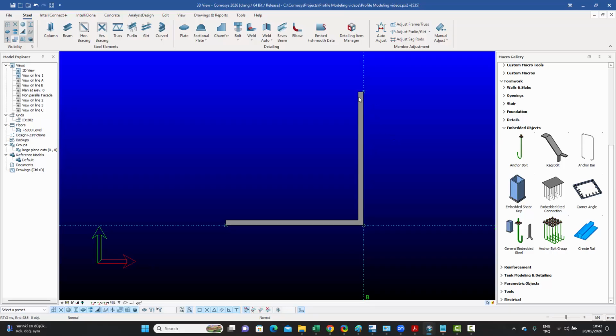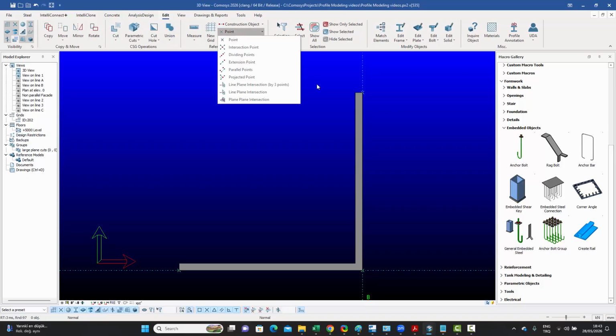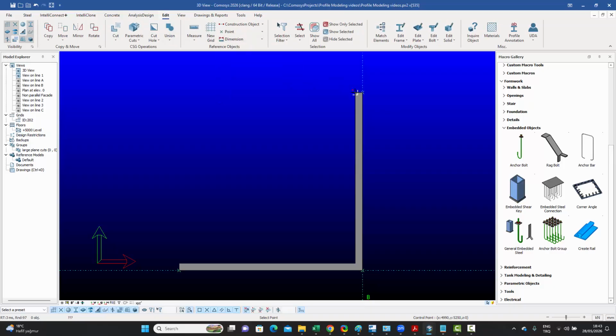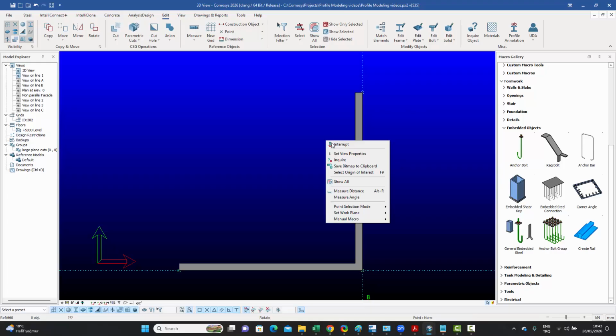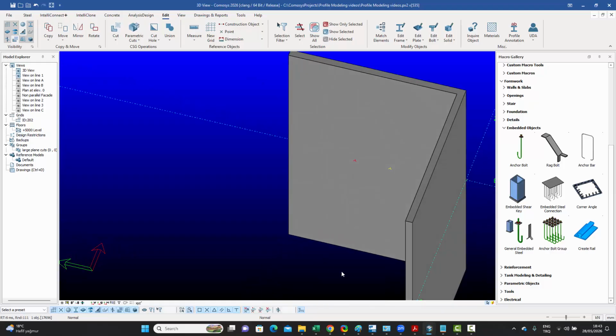So we have the numbers now, and now we can create basically the 0.95 down from here. So what we can do is hover over this point and say dy minus 95 to get the first point, and then hover over this point and say dy minus 50 to get the other point, like that. And we can actually create those bars.